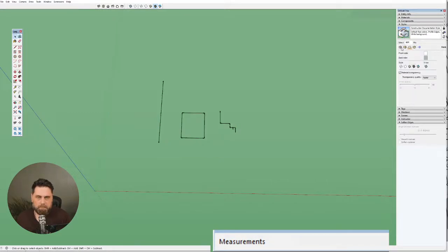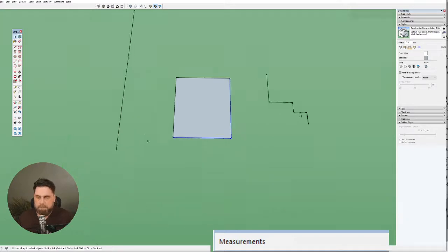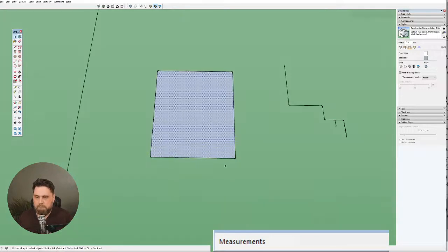So then in our face styles, we have our face edit styles edit options. We have the ability to change. In SketchUp, there are 2 sides to every face, a front and a back. So we can adjust the front color and the back color separately. The default is this light blue. So if I look at this face, it's actually backwards because it's light blue.